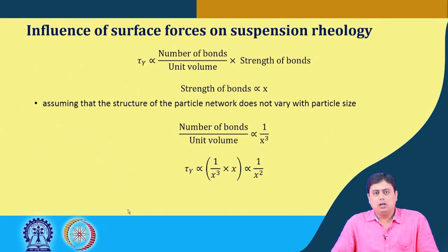Now, in terms of the particle size, how is it influencing the suspension rheology? In the case of the hard sphere approach, there was no influence of particle size on the suspension rheology.